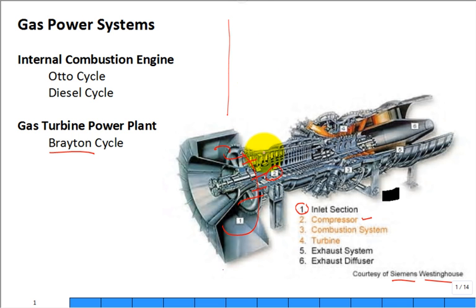Often it has multiple stages of stators and rotors, rotating blades. It catches it, turns it with an angle, catches it, turns it back. In fluid mechanics, sometimes you wonder, why are we studying vanes so much? And you have a jet of fluid hitting a vane. Well, this is why. That's what's happening. Even though it's axial flow going this way, it's always changing back and forth.